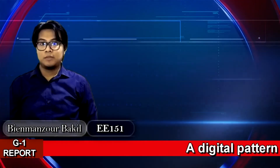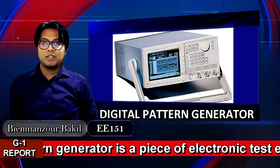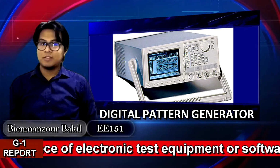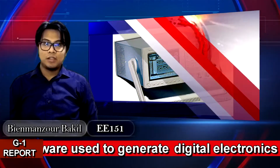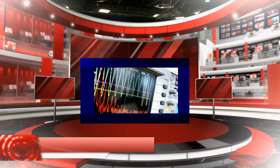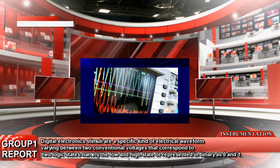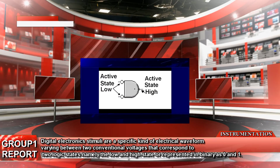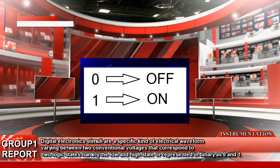Now for the next one, the digital pattern generator. The digital pattern generator is a piece of electronic test equipment or software used to generate digital electronic stimuli. Digital electronic stimuli are a specific kind of electrical waveform varying between two conventional voltages that correspond to two logic states, namely the low and high state, or represented in binary as 0 and 1.